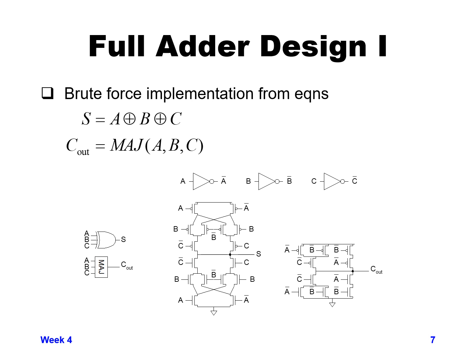A different way we could have done it, like I mentioned before, is you could do a 2-bit XOR in one stage followed by another 2-bit XOR in a second stage. That might be a little bit more delayed than a single stage. So this could be a way to do it in a single stage a little bit quicker. The circuit on the right is a way to do a single-stage 3-bit majority function to get C out. So this is possibly the quickest way to get a sum and C out in a single stage.